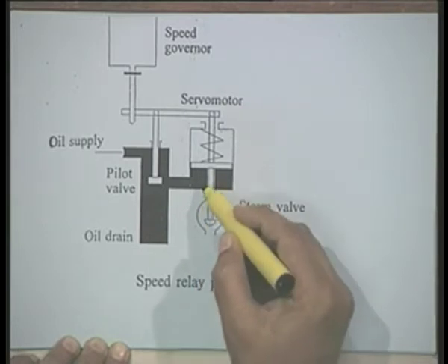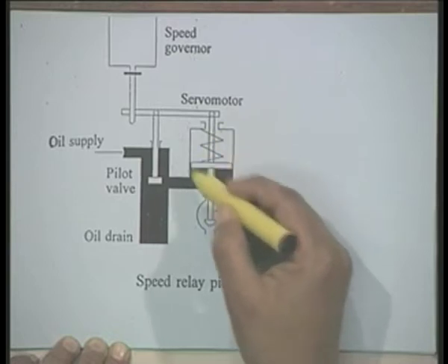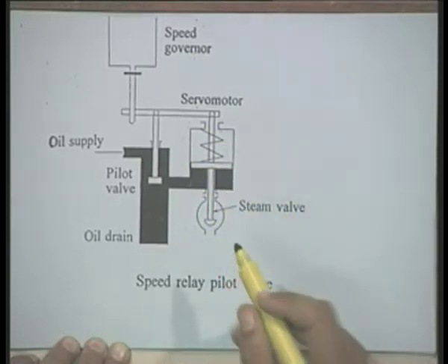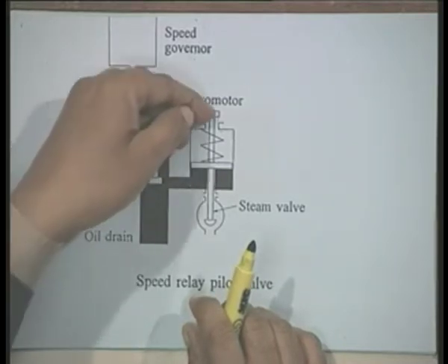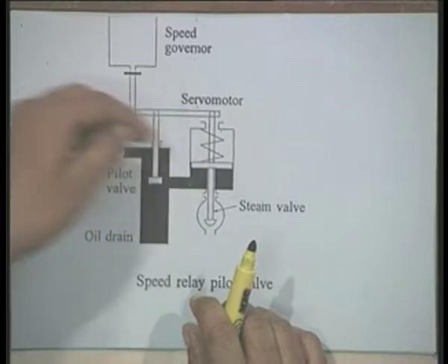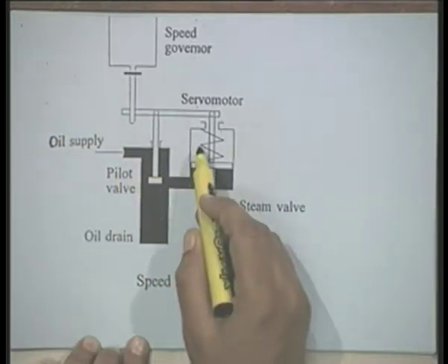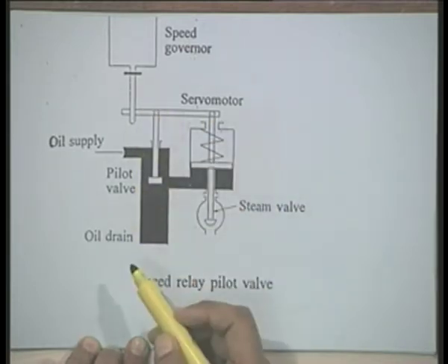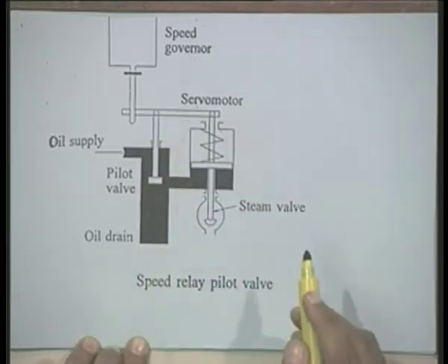The movement of this piston when it is moving up is restricted or controlled by the spring pressure. Okay. Now, you can easily see that when this is trying to move, this will also come down, while at the same time when this oil enters and tries to push it up, through this same mechanism this pilot valve is also pushed up. Therefore, this acts as a negative feedback.